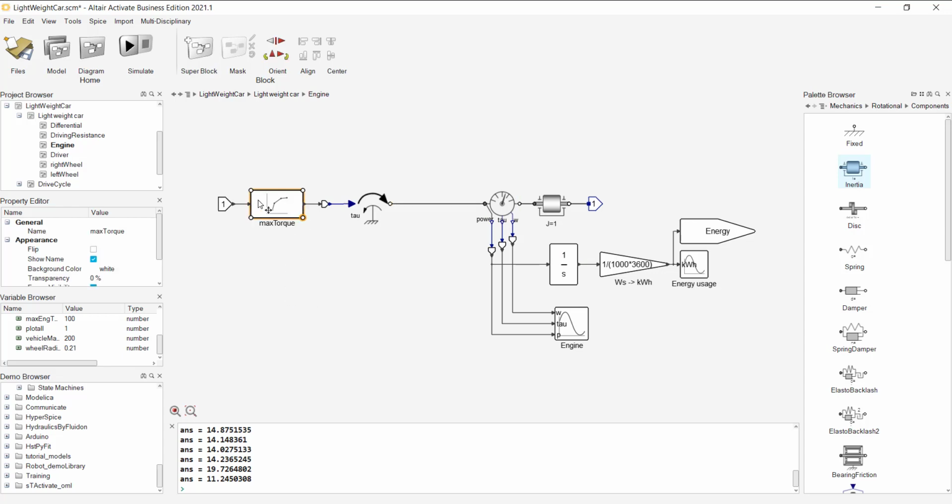And a lookup table here. So we have our accelerations coming from our gas pedal, which is going into a lookup table, which is an acceleration versus torque table. So from that, then the output of this will be our torque applied.